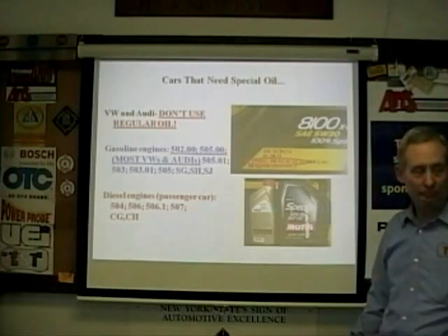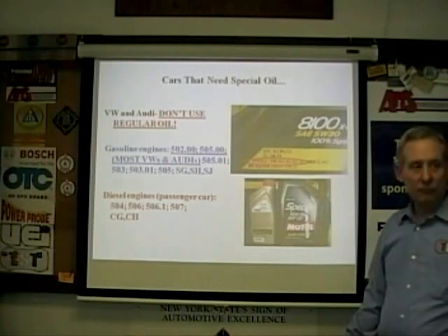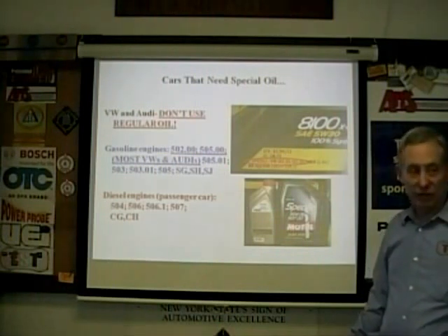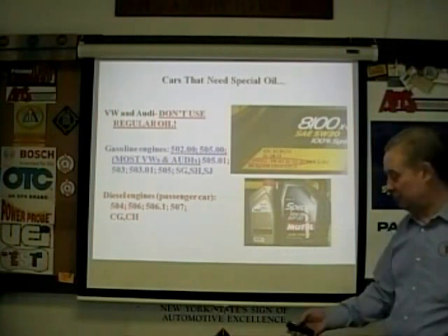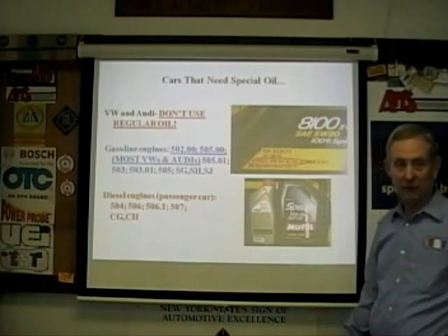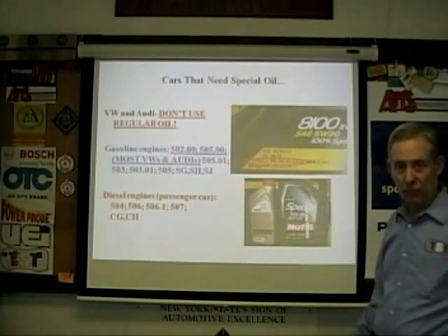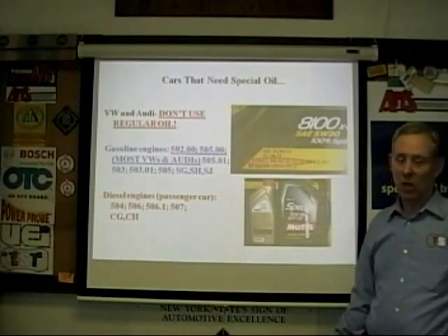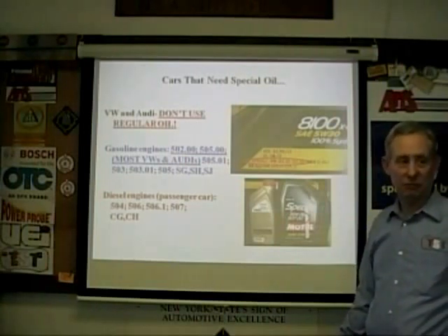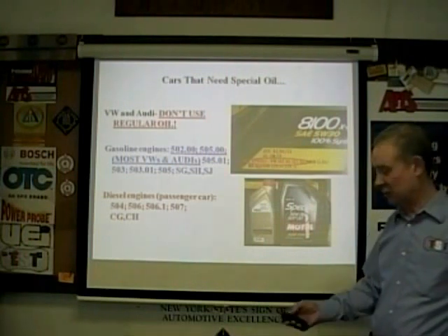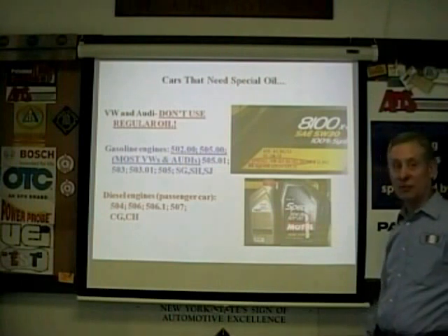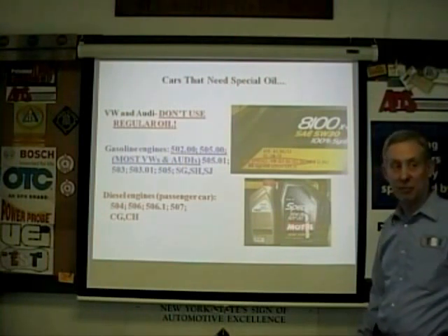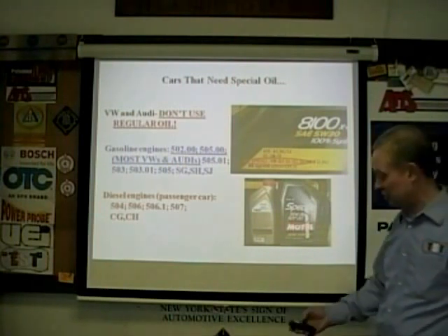So you would say a good starting point, if you do have a code for variable valve timing, the first step is to check the oil. Check oil pressure, make sure it's got the right oil in it, and if in doubt, drop the pan and look for debris in the pickup, because it may be too late at that point. There's no easy way to check what the weight of oil is, right? No, you just have to take it out and put the right stuff in and see if the symptoms go. I've actually had that. But in my opinion, anytime you have something like this that you're worried about, you should be dropping the pan and physically examining the bottom to see what's in there.